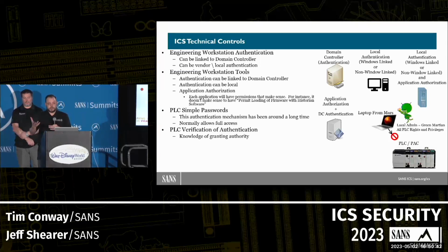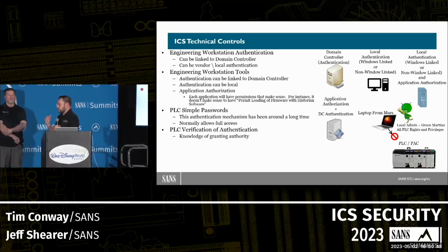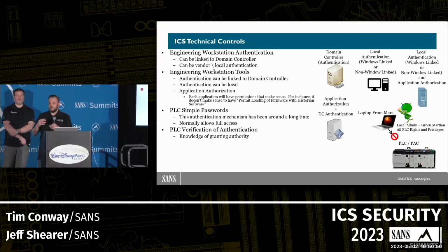If you think of Active Directory or LDAP or a directory model, companies like Rockwell have tools like FactoryTalk Admin, and you can start to configure which engineering workstations can talk to which devices and which devices can talk to which devices in the field. You can enable an entire authentication and access model at the industrial control system level, working with a number of your vendors. And if you did that, you would be adding tremendous amounts of security.